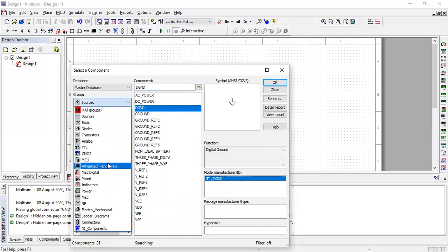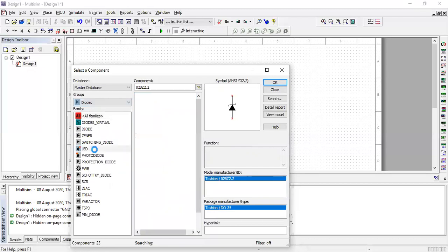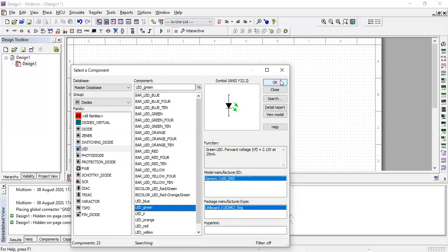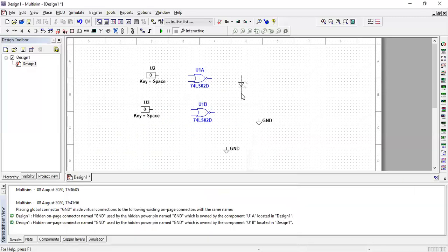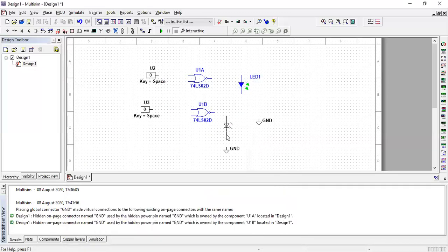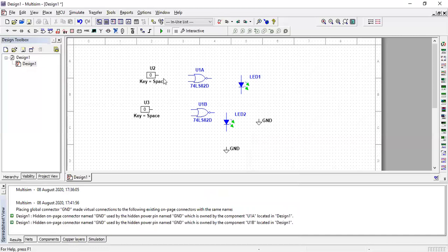and to the output side we are going to connect LEDs. We are using green color LEDs. So two LEDs are connected for the output, as there are two outputs in any flip-flop, which are Q and Q bar. So let's now connect the input to the NOR gate, and the second input to the second NOR gate.